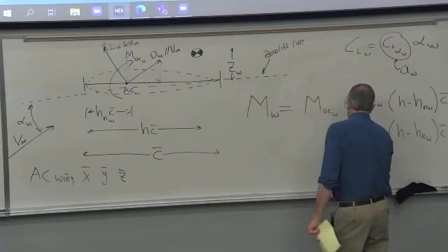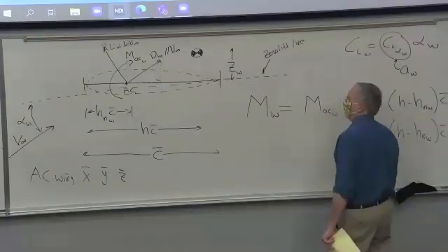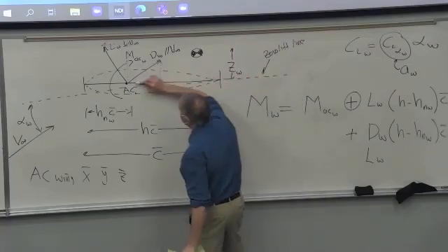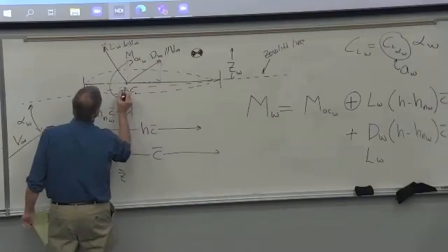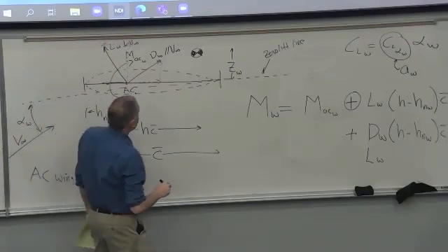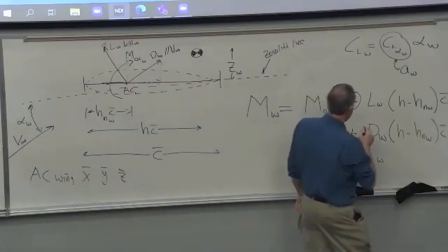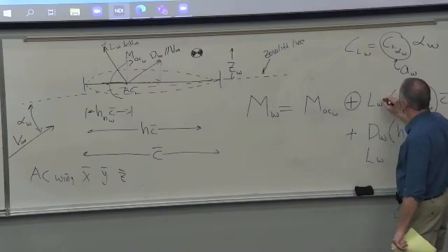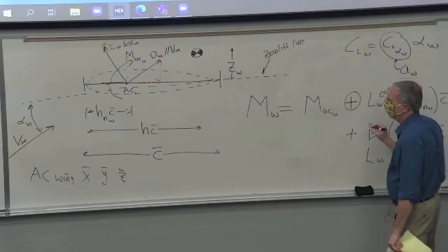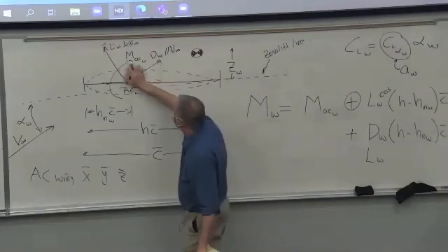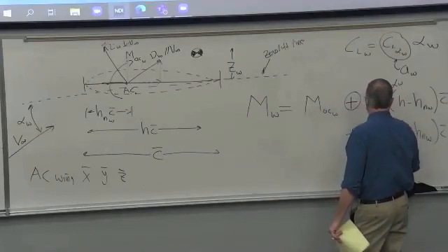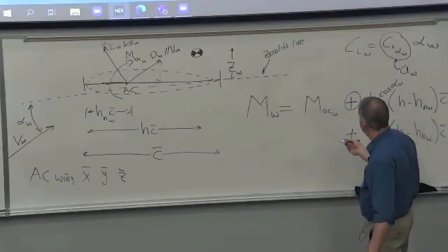Now I've got the horizontal component of the lift times, and its moment arm is ZW. It's acting down here, right? The component is acting here times that distance, so that's nose up, right? Oh, I forgot to put my signs in here. Hang on. This is lift of the wing. What's the component here? Sorry about this. That's cosine. What angle? Yeah, this angle here is alpha because that's how much that tilts over. Sorry, I confused things. Cosine alpha wing.